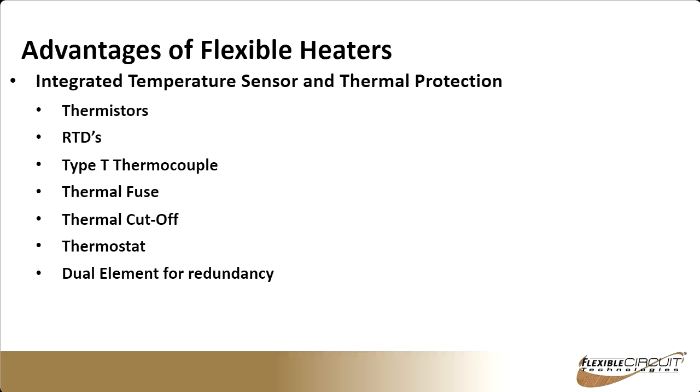Thermal fuses could be etched in or soldered on. Thermal cutoffs, and over the years, these have gotten to be where they can be resettable as well. So if it gets to a certain temperature, the device would shut off. Most commonly, they're just controlled with a controller circuit, but the option to add an extra layer of protection is there. We could put a thermostat on them, and then we could create dual elements for redundancy as well.